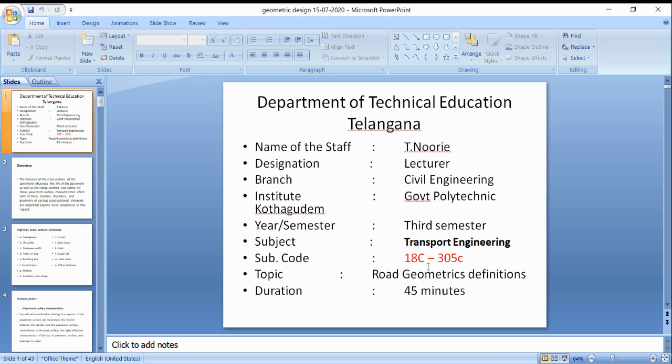If the subgrade is strong, then there is no need for a subbase. Its function is to protect the subgrade, and it will improve the drainage facility. If a subbase is kept, it will reduce the cost of the pavement also.